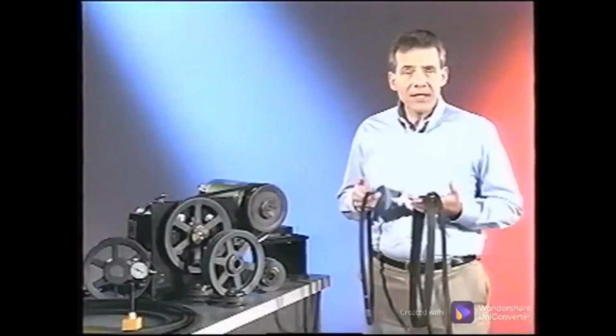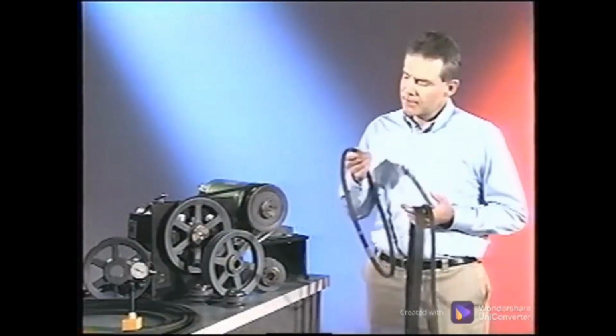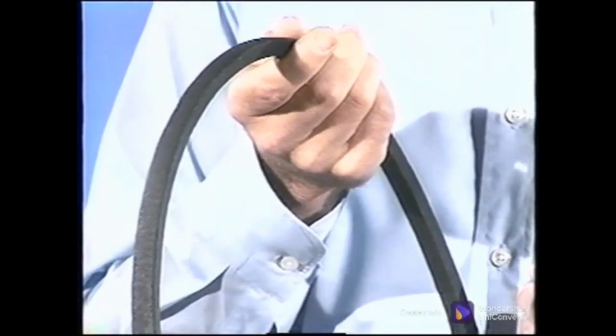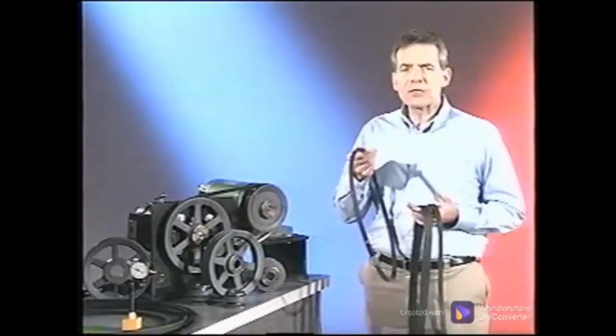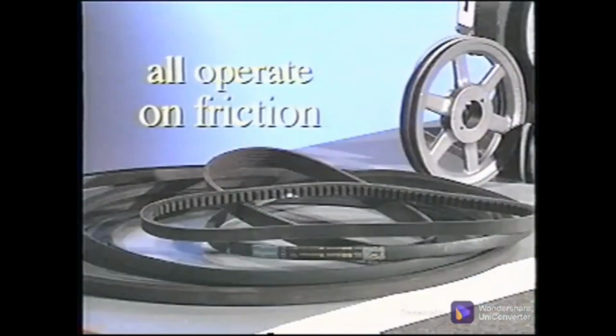It is important to know the design of belts and to understand their operational characteristics in order to better recognize and correct belt problems. Belts come in many shapes and sizes to accommodate most power transmission requirements. The V-belt is the most common, while variances to it are used in special applications. V-belts can operate at speeds up to 6,600 feet per minute, while a cog belt and a ribbed V-belt can run much faster. But they all operate on the principle of friction.